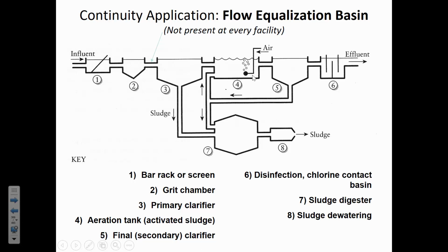So if you think about how wastewater is generated, it's generated by people washing dishes, taking showers, flushing the toilet, and all of those things vary quite a lot over the course of a daily cycle, where in the middle of the night, if you're asleep, you're not using water. Maybe you have a small drip from your foundation drain that's contributing some base flow into the sewer treatment plant, and there might be some industrial operation where the people are working all night long, and so there could be some flows from that.